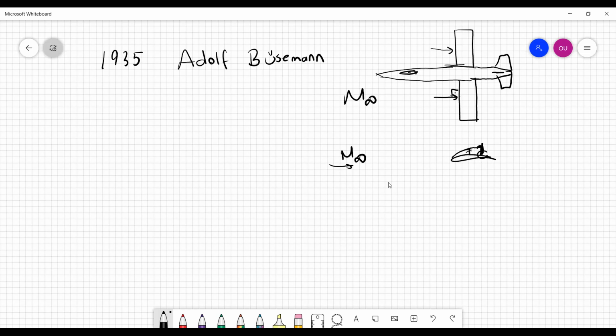If you zoom in on this region, let's say this is the top of the airfoil, we have a shock wave somewhere in between. You have this flow coming in, and we have been doing our compressible flow analysis based on an inviscid flow assumption, but of course, in reality, flow is not inviscid. Flow is viscous, and that generates what we call a boundary layer on top of the airfoil. We will see those in detail in coming weeks.